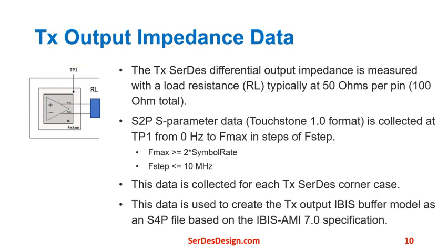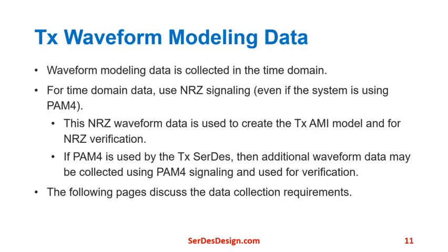This data is used to create the transmit output IBIS buffer model as an S4P file based on the IBIS-AMI 7.0 specification or later.